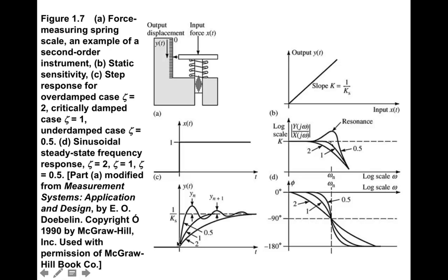In the critically damped case, you basically have an optimized trade-off where the rise time is as fast as it will be here without oscillation. So if it's critical that you not overshoot your final value and you have no oscillation, but yet you want as quick a response time as possible, the critically damped system will give you that. And then finally, the overdamped system has a slower rise time and a smoother function and also no overshoot.